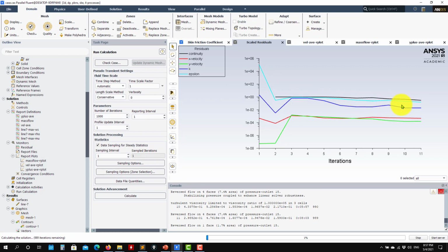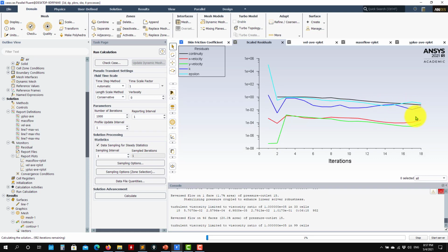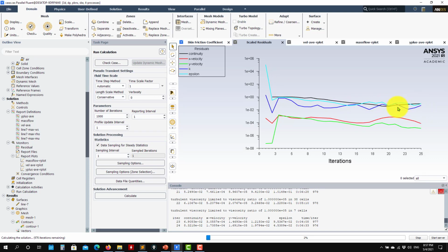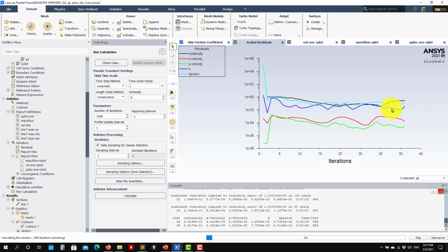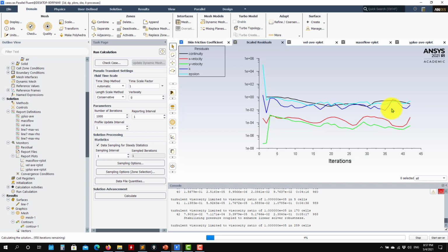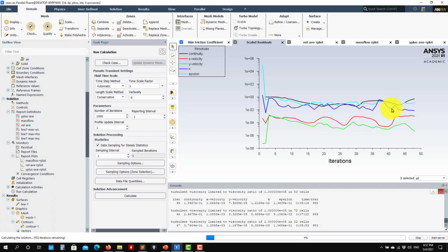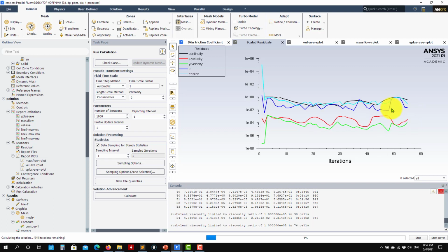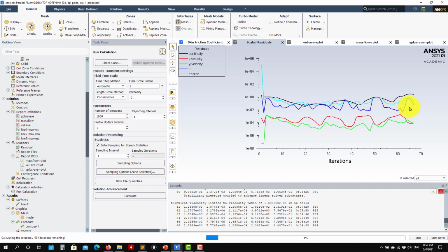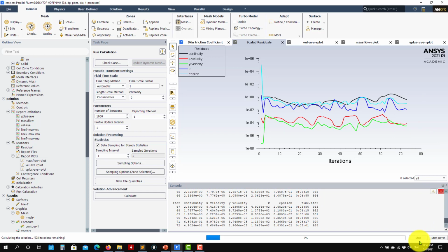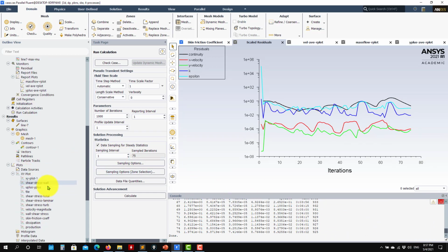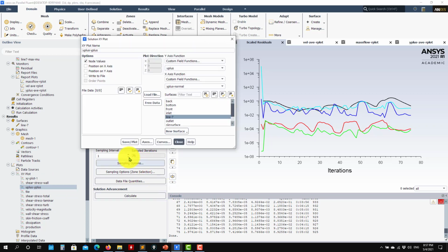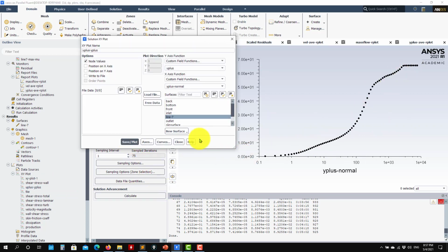Okay, so just erasing that solution, maybe that was the influence, but I'm sure that I'm not going to get good results because I'm using the standard formulation of the K epsilon with wall functions. And that one will have problems getting a solution with a wall resolving mesh. And as you see here, we already see that we're having problems converging. So at this point, you could stop it, and as you go and start to do these plots, you will see that you have these strange plots.